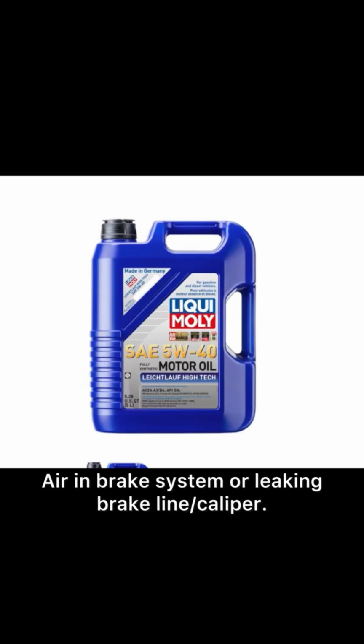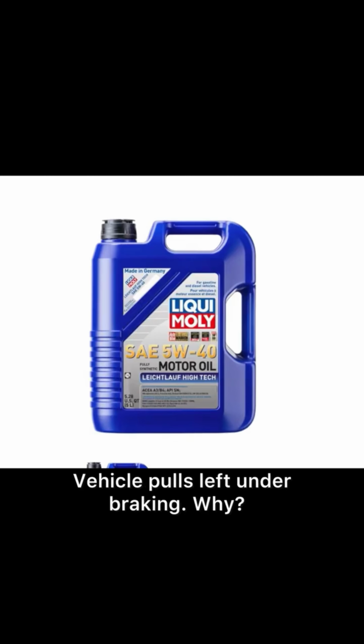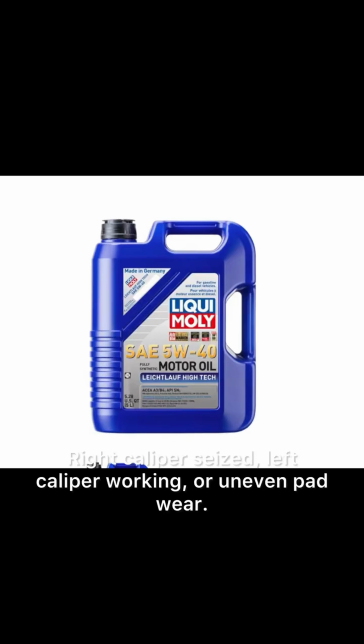Brake pedal sinks slowly when held down. Diagnosis: internal leak in master cylinder. Vehicle pulls left under braking. Why? Right caliper seized, left caliper working, or uneven pad wear.